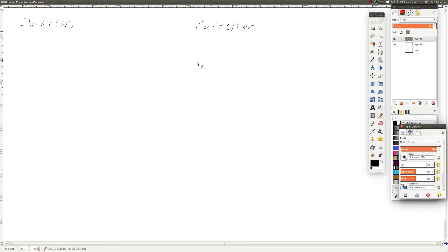So, the easier thing to talk about is actually capacitors, so I probably should have put those on the left, but oh well. How does a capacitor store energy? Well, we're going to talk about the parallel plate capacitor. What that means is two large metal sheets with a space between them referred to as an insulator. So this gap here, which I'll erase because I'm going to want to draw in there actually, there's no current that can move through there. These are, in effect, electrically isolated.